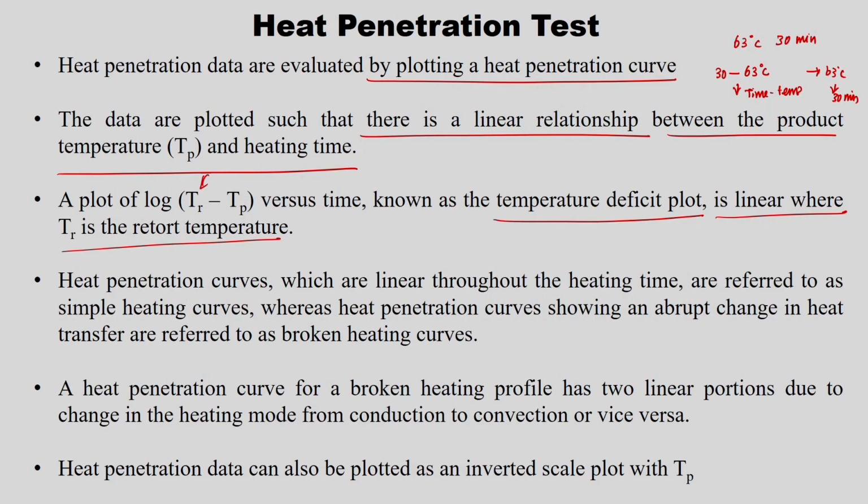Heat penetration curves which are linear throughout the heating time are referred to as simple heating curves, right. So, that is if you are following only one particular mode of heat transfer. But if there are any changes, from conduction to convection for example, I have a container in which my liquid and the solid particle are there. First the heat I employ through the retort has to conduct through the walls, and from the walls to this liquid medium it is a convection.